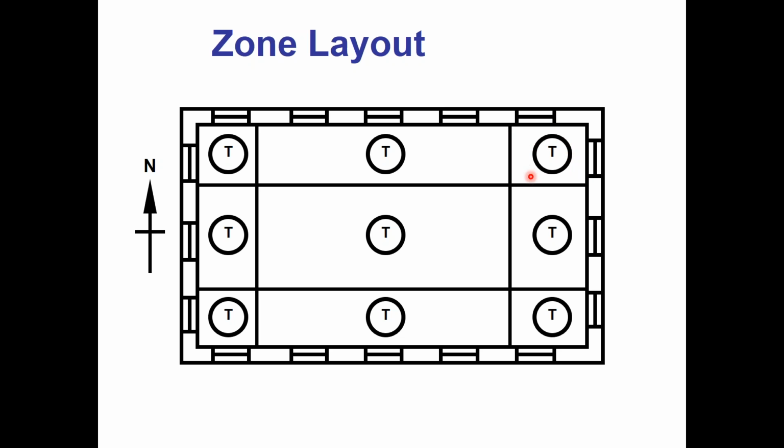Now, that room could be something else. It could be a storage room. Okay, well, if it's a storage room, then I really don't care that much, and I would go ahead and combine them with somebody else. If it's a private office, I probably would care. This big interior zone, I don't have any dimensions on this drawing, but if this was a really, really large space, maybe instead of one big zone with 5,000 CFM, I would want to divide it up and have 3 or 4 zones taking care of that.